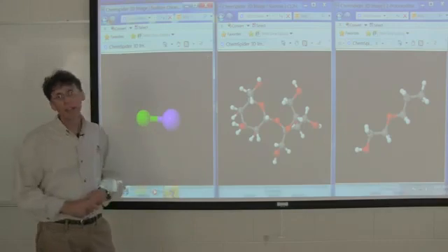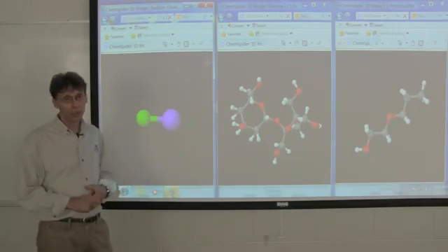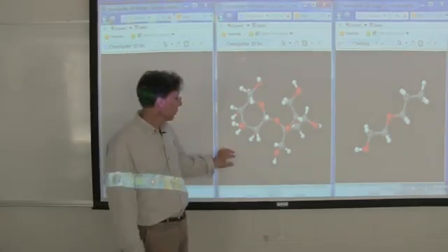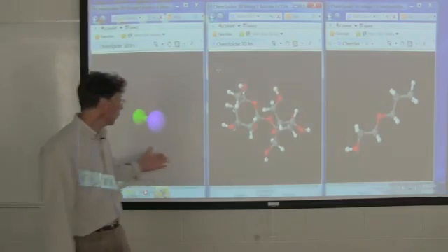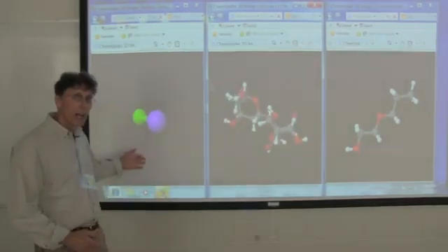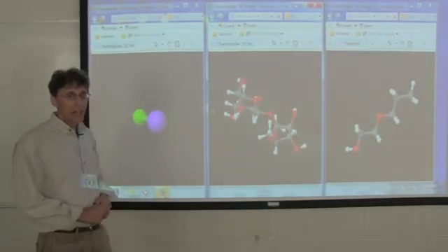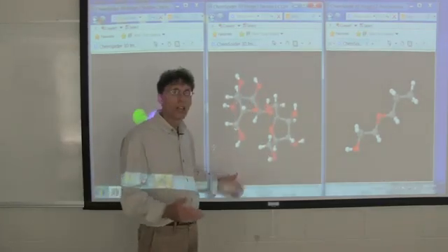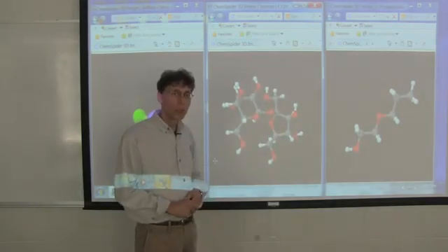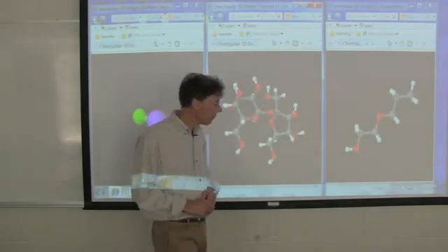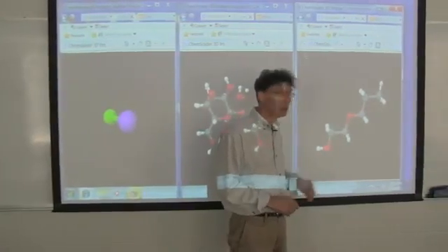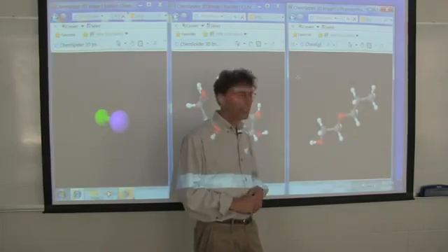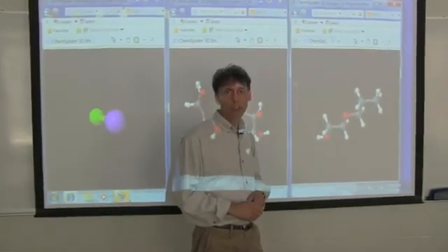Ones that perform better than these, or others that are presently known. This is sodium chloride, an inorganic molecule. This is sucrose, an organic compound. Both of these alter set. Sodium chloride accelerates set, makes Portland cement set faster. Sucrose retards set, or makes Portland cement set or harden slower. Another organic compound, 2-propoxyethanol, actually hardly affects set at all. Instead, it's used to reduce shrinkage.